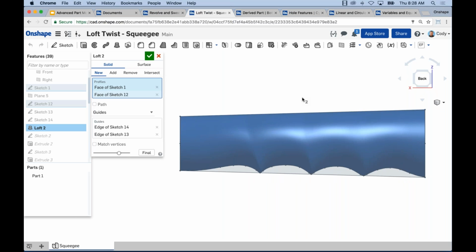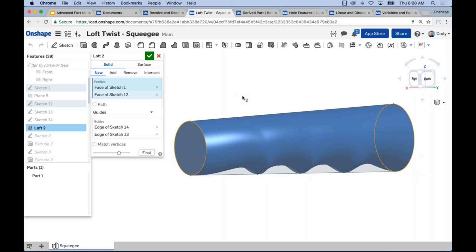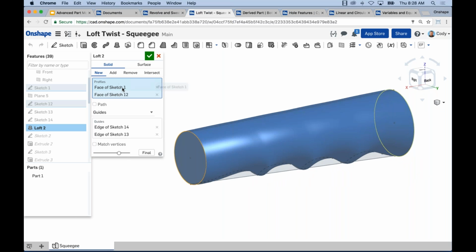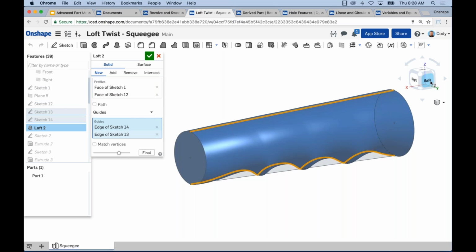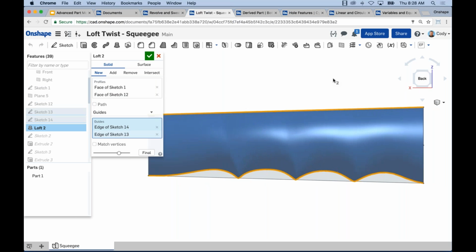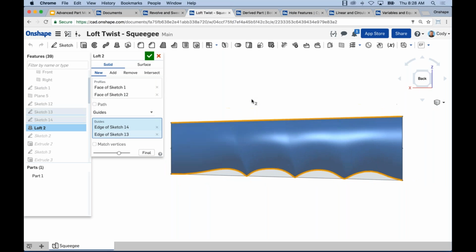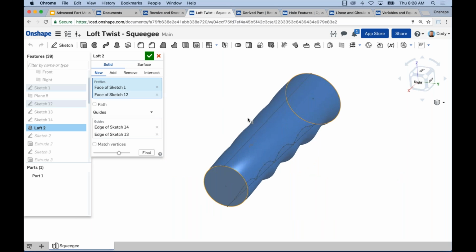So how do we accomplish this? Well, we use a loft. The loft is really just a loft between two circles, a circle on either end, but it's controlled very specifically by two guides. These guides control the shape as you're transitioning between what is essentially two simple circles. So just keep in mind, these kinds of shapes, loft shapes in general, will require multiple pieces. As you can see, I have four sketches to construct this handle, but you really couldn't do this any other way.